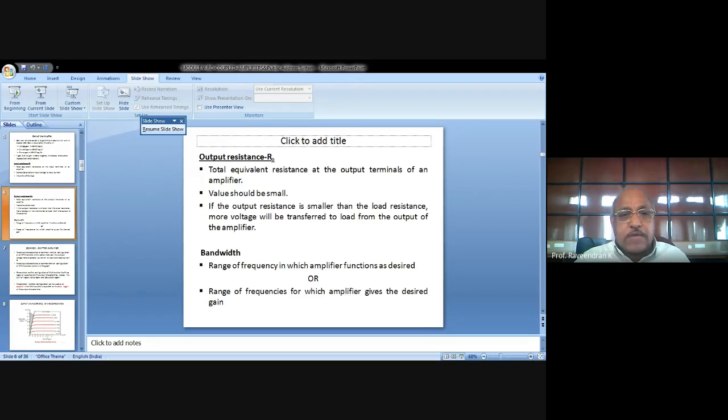If you consider this as I2, then strictly speaking I2 must be I1 plus IB, isn't it? No, I1 minus IB, not plus. I1 is coming here and IB is flowing away here. At the junction, I1 divides into I2 and IB.